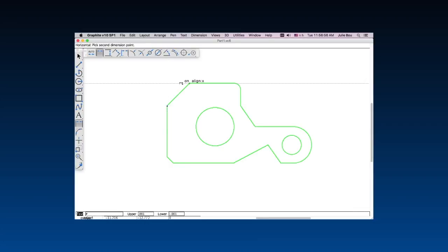Going back to our drawing, I'll now click the upper endpoint of the 45-degree line. Our dimension appears, but let's change the text. Move the cursor over the characters and the selection pointer appears. Drag the text to the left horizontally until it's about ½ an inch from the left leg of the dimension to reposition it. Next, we'll dimension the vertical edge to the base of the part.